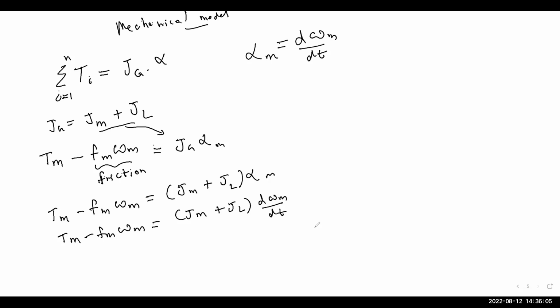Now for this, we'll apply the Laplace transform. You might be wondering why. In the earlier case also, whenever there was an inductor or a velocity term, I went and applied Laplace. The reason is that we don't want to work with differentiation terms, because whenever there's a differential term in the equation you have to use differential equations to solve it, and we don't want to make things complicated. It's better to have it in algebraic form, so we use Laplace to convert it into algebraic form. There's not going to be any difference here because we have only one differential term, and we'll get this.